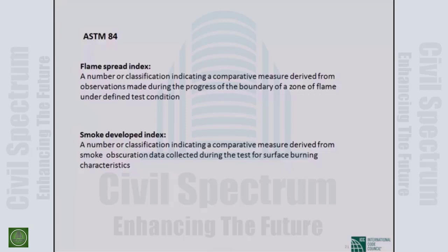For the transparency of the smoke, you give a relative measurement, and it will give you an index value that gives you some understanding of how much smoke is generated by any material, but it does not measure the toxicity, it measures the density of the smoke only, and this will give you some index value.